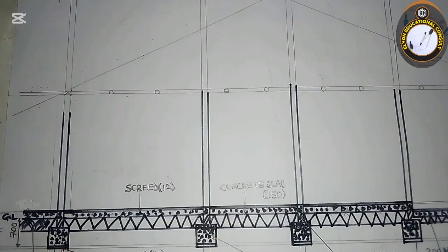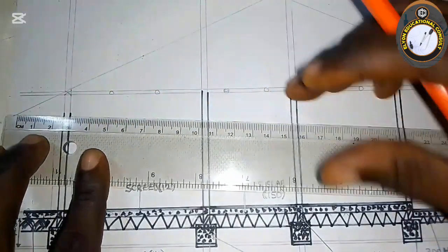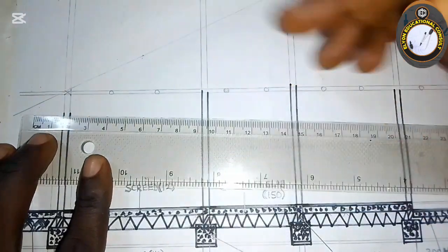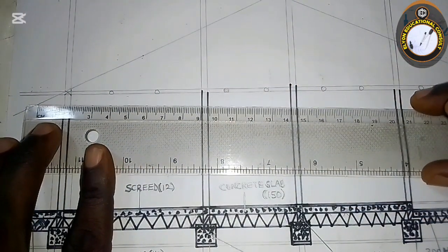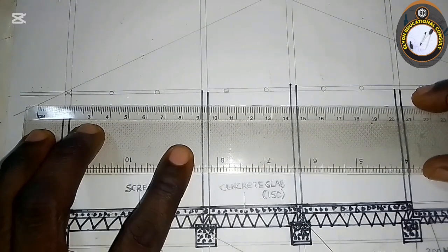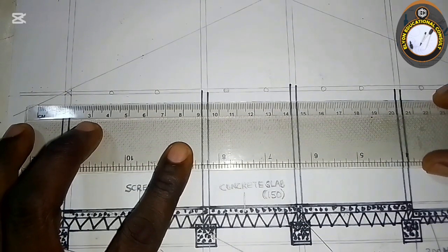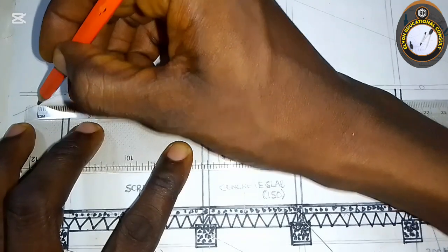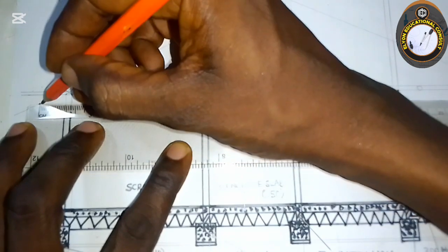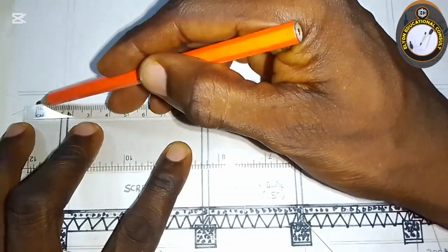So to take the eave from this external wall, I'm going to take 1.4 to where the roof ends. I will just go this way, so this is 1.4 to this part here. So this is the eave projection at this point here, and that is where we have the roof span to.